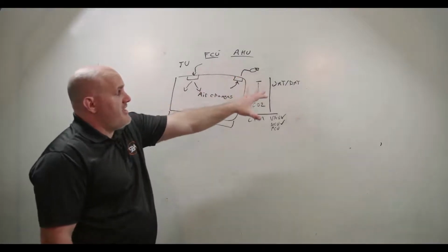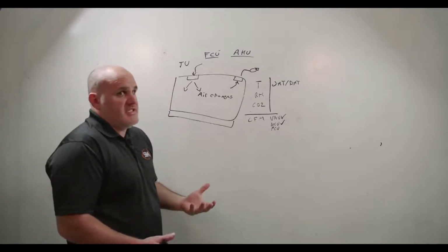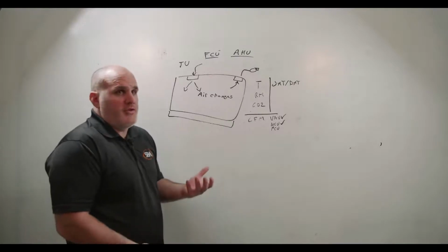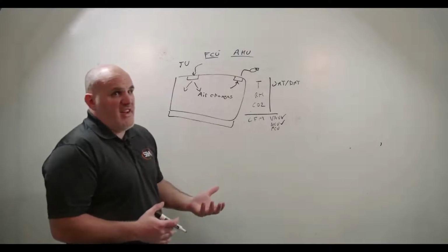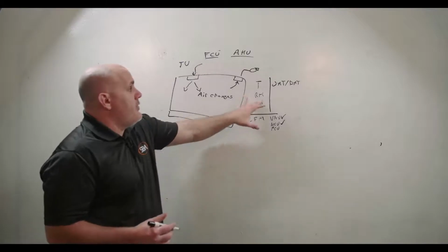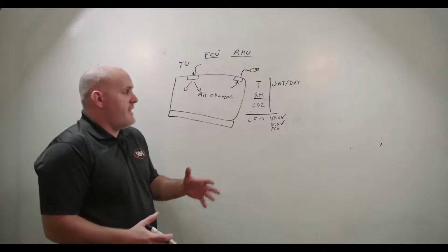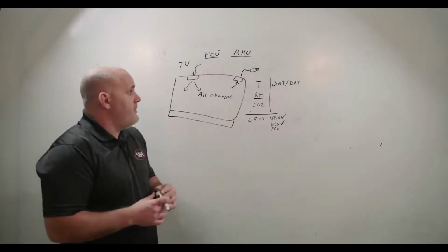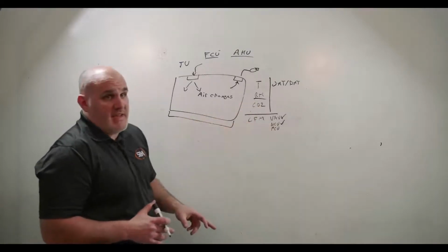And you condition that supply air, discharge air temp, and based on whatever your sequence is, whether you're doing a reset, which would be in like a constant volume scenario where you're doing 55-65 reset, or in a variable volume scenario where you're doing 55 and just driving the saturation so you can bring the humidity down and kind of control the temperature. When we talk about relative humidity, we'll cover this in much greater detail in our psychrometrics video. I think the psychrometrics video is the very next video.